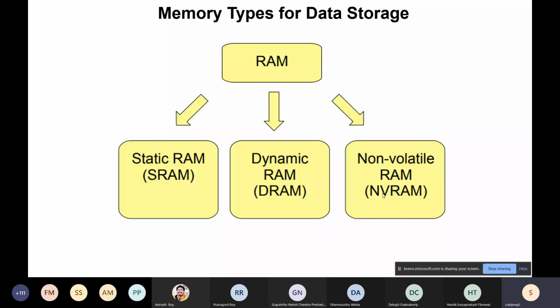Reading from any memory is possible byte by byte or word by word, that means 16 bits at a time or 32 bits at a time. So all these advantages of the different memories, from non-volatile to volatile, are actually combined in NVRAM. The MSP430 from Texas Instruments is one of the microcontrollers featuring this. There is something called ferroelectric RAM, FeRAM, which is a type of NVRAM.